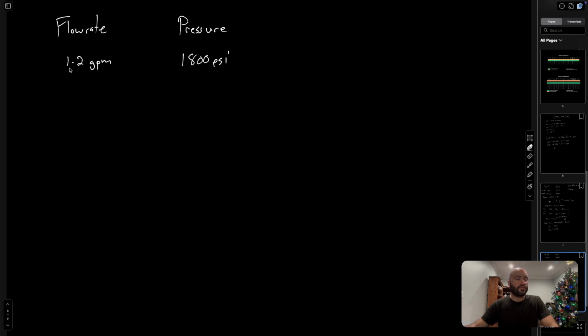right? And then we have other pressure washers that are 2 gallons per minute and closer to 1000 PSI. Something that has been taught, I guess, in the detailing world is something called cleaning units. Right. And cleaning units are when you take your flow rate and multiply it by your pressure.